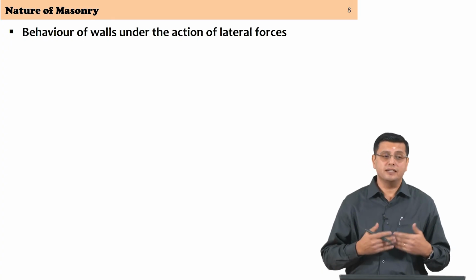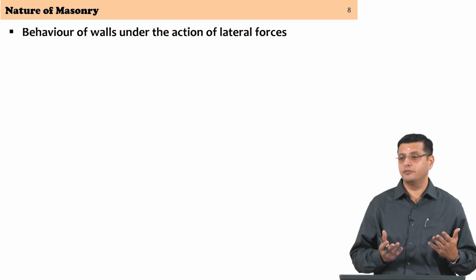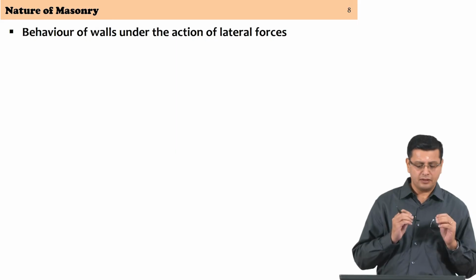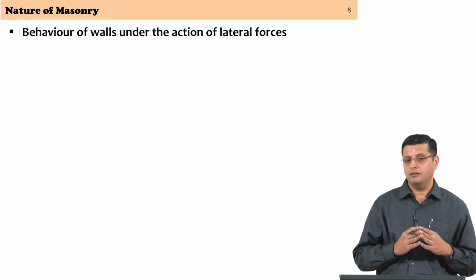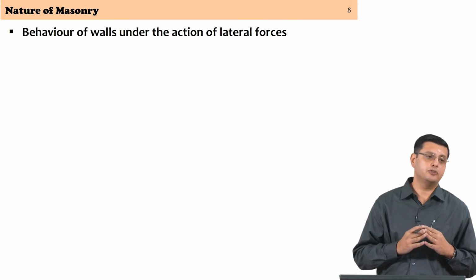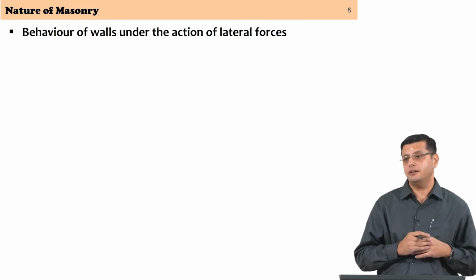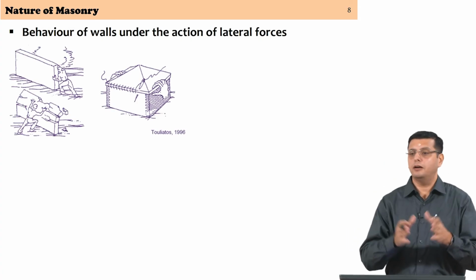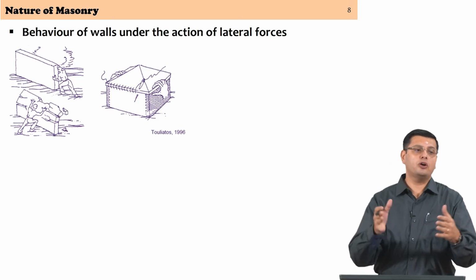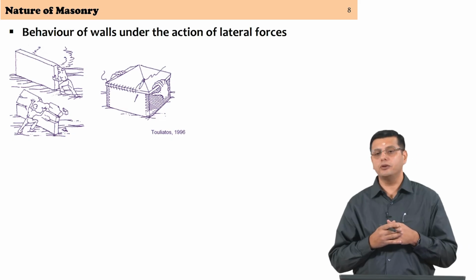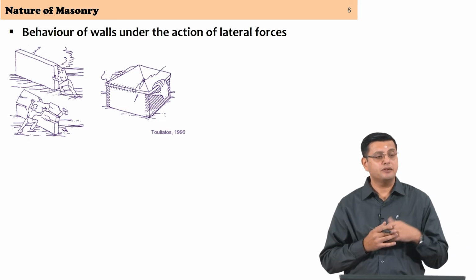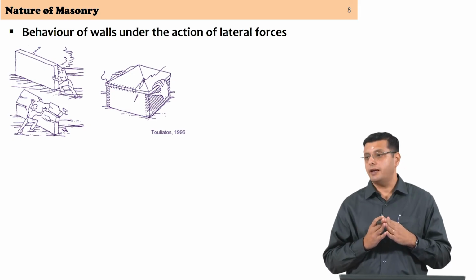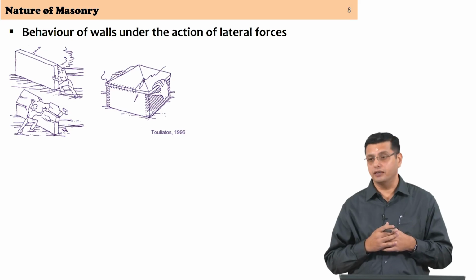Within the resistance of a wall to lateral forces, there is a certain difference that we have to examine, and this is another aspect of weakness which becomes essential to keep in mind, because it keeps coming back to us in earthquake resistant design. So, if you were to examine a masonry structure as composed of 4 load bearing walls with a roof, and we have seen a picture where separation between the orthogonal walls happens under the effect of lateral forces like earthquakes, right.